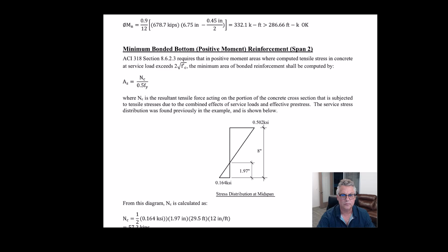in the positive moment regions. Please don't do that. Let it get up to 6 if it needs to. Put in the bonded reinforcement. In fact, we won't do a two-way slab design that doesn't have a mat of bottom steel in both directions. We will never be less than 4s at 30 in both directions. Need it or not, that's what we put in.